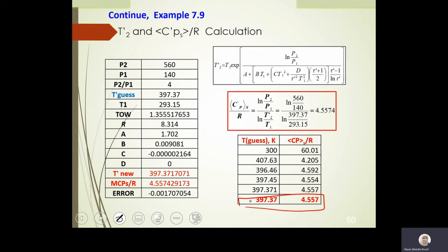Okay, to integrate this equation, I consider Cp constant and beta, which is normally the case in pumps, can be considered constant. And the volume is also constant because I have liquid phase and I can consider it incompressible here. Volume is not changing significantly, so I consider it constant.